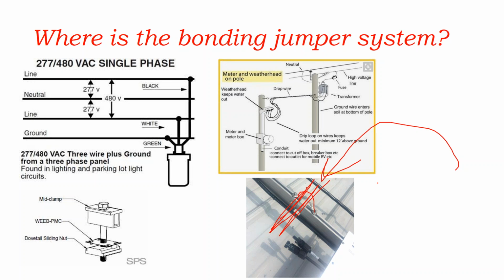But what about if I have a pile that's driven directly into the ground? Is that a grounded connection? Or if I take a stick of metal and another stick of metal and I just touch them together, is that a bonded connection? And the answer is, well, it depends. And it really depends on if it's listed for that.